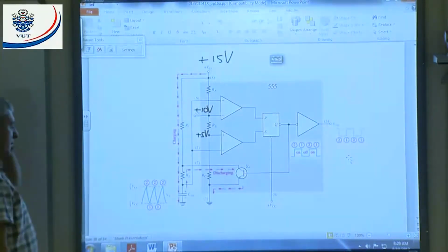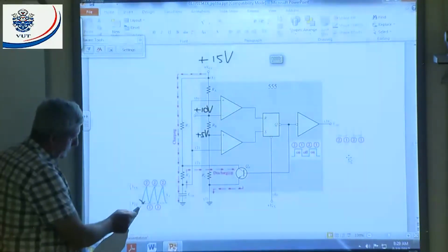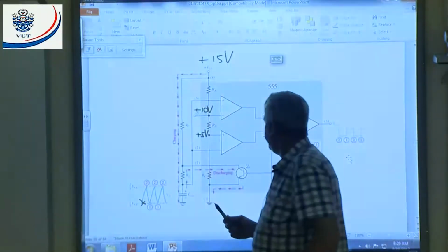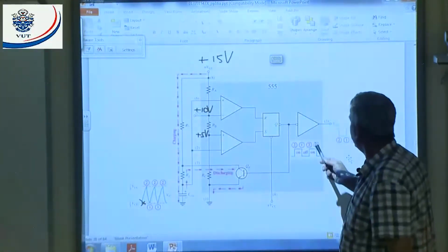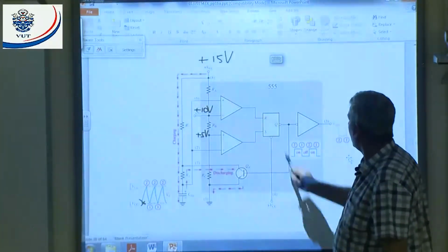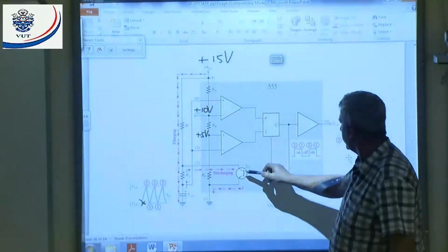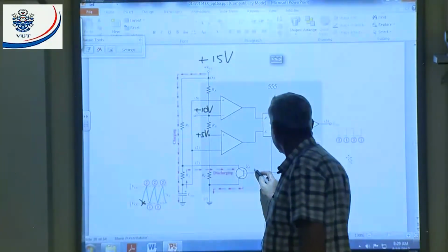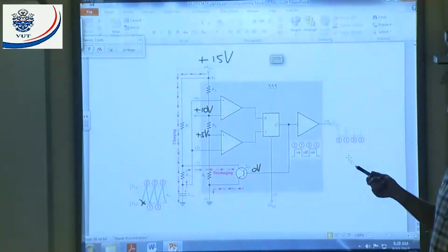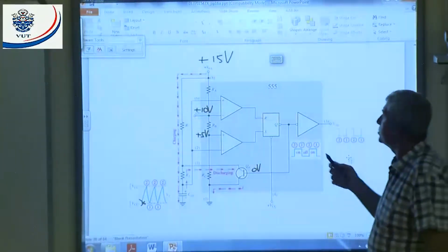All right. Now, let's consider a starting point. We're going to start there. When I start there, we must assume the Q output is going to be a 1. That means after the inverter, I will give a 0, or low value, there. That transistor will be off. What will happen? We will start charging.